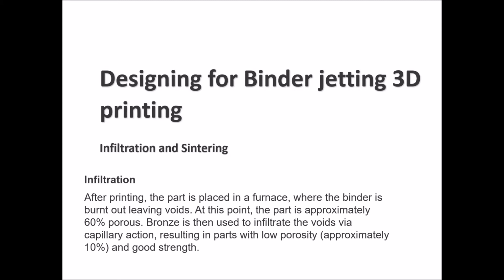Infiltration is usually done after printing, so you put your part in a furnace and the binder will be burnt so that it will leave some voids. After that, the part will be up to 60% porous. Then we will use a bronze material that can infiltrate the voids through capillary action.